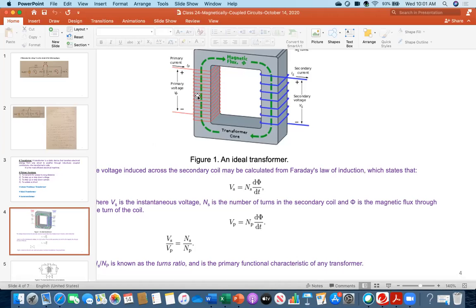Even though you apply it, if you use a voltmeter, you will get a 0 reading, for both ammeter and voltmeter. The adverse impact will be, if you put your hand on this body, gradually it will be heated up because of that flux. That is the property of magnetic material: even though it's a steady or constant voltage, constant flux, gradually it will be heated up. So that's why it is not advisable to apply DC on the transformer.